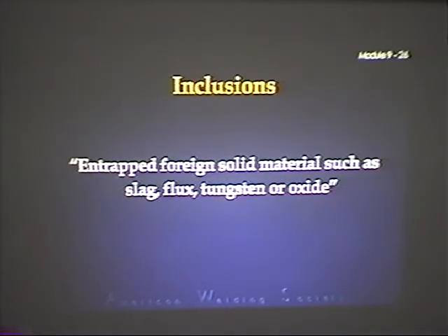Slag inclusion. Slag trapped in the weld. Exactly, slag trapped in the weld. That's the most common that you're going to come across. It says entrapped foreign solid materials such as slag, flux, tungsten, or oxide.